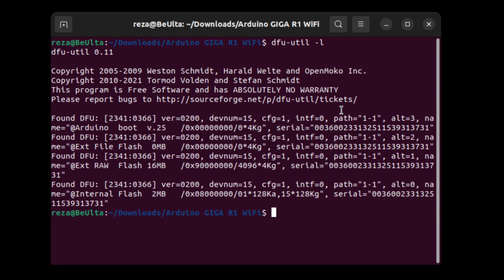You can obtain a list of all the devices connected to the desktop for flashing by dfu-util by using its -L option, -L for list. In this example, there is only one device connected, but the device has 4 different partitions and they are serialized from alt setting 0, 1, 2, and 3.